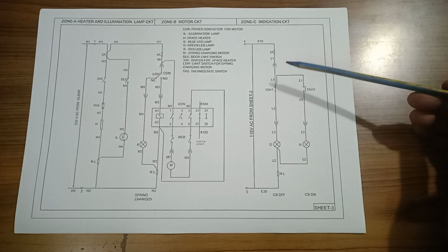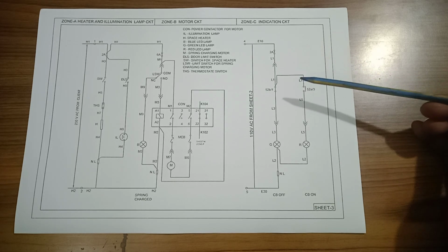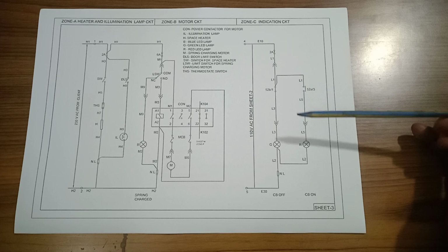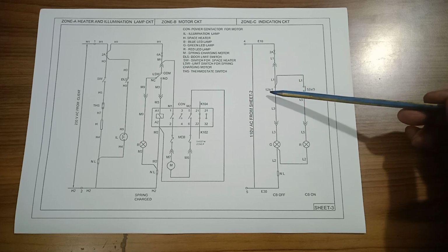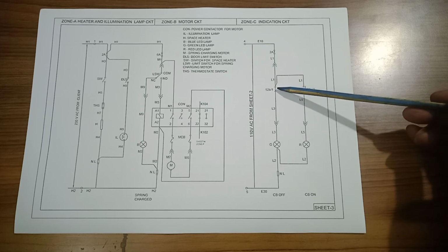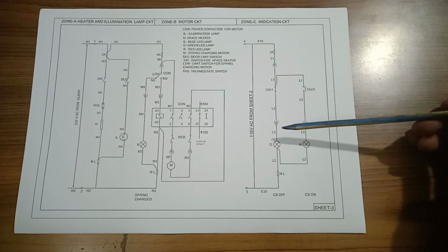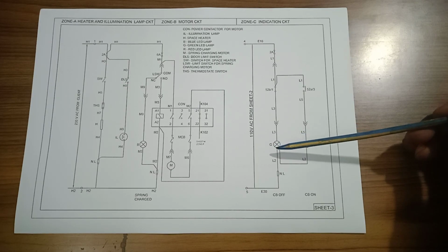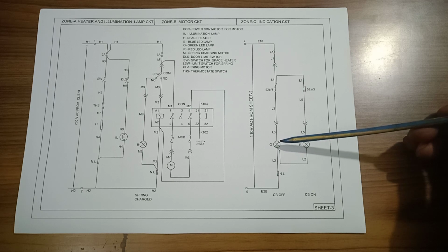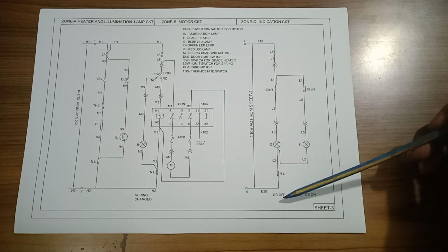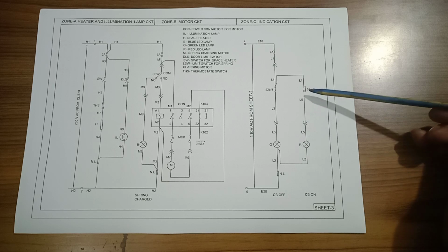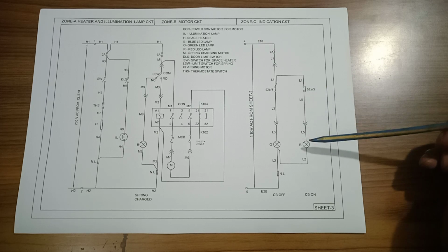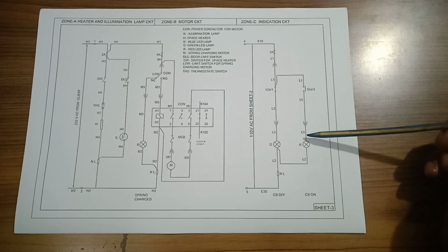After the circuit breaker is tripped or opened, 52B by 1 is an NC contact and the green LED glows, meaning the circuit breaker is in off condition, and the red LED is off.